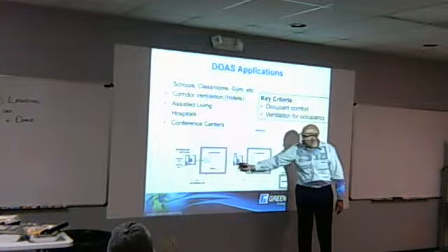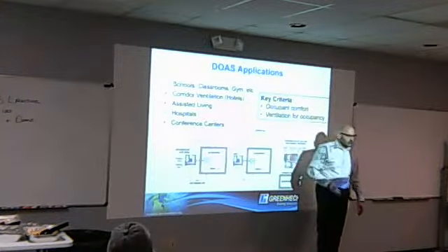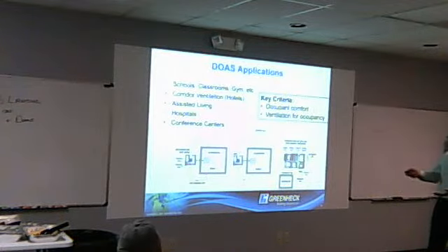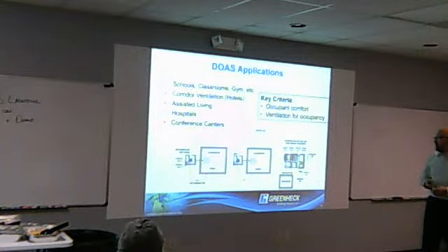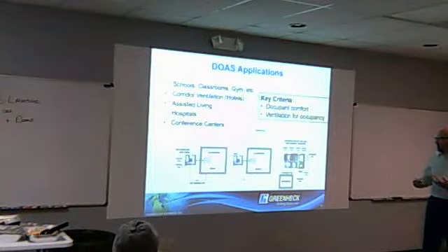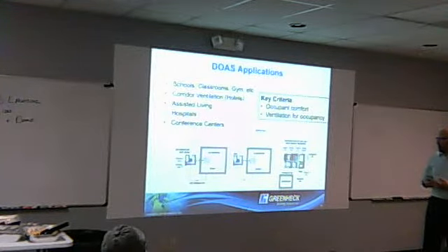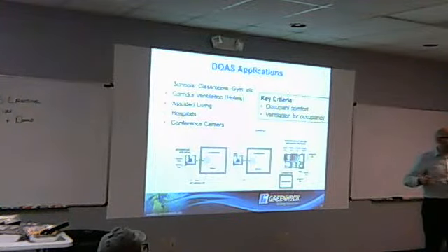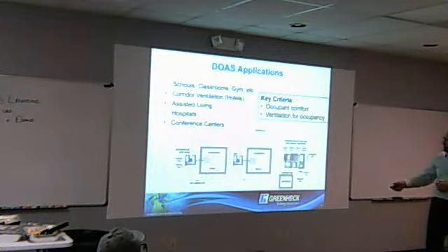Then in the space, you might have a sensible unit just to do your space load. So that could be a small air handler with the cooling coil. It could be with the heating coil. Also, it could be a fan thermal box that has a sensible coil on it. So it could be ducted that way. There's a variety of ways to accomplish this, but it's just to show you the idea.